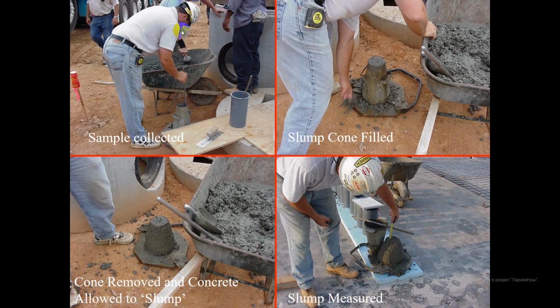Here you can see a sample collected. Slump cone filled, cone removed, and concrete allowed to slump. And here the slump is measured. So testing of concrete we already understand.